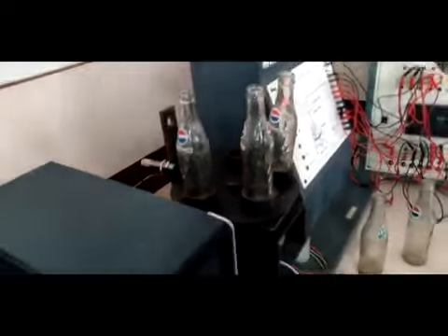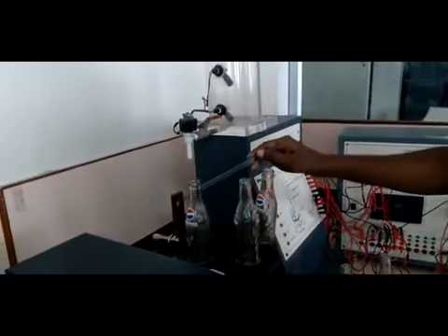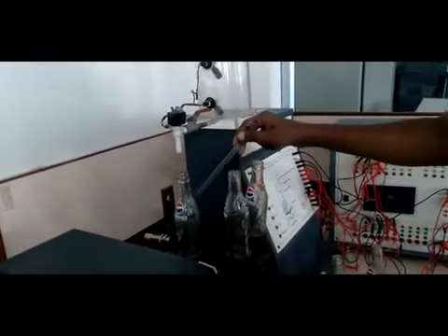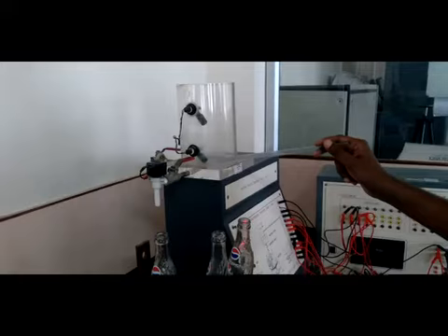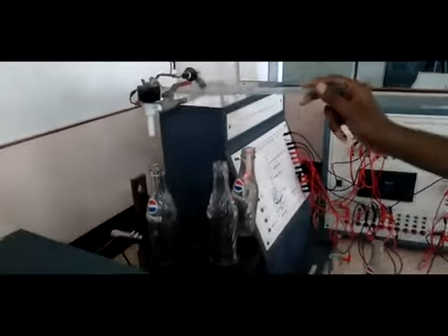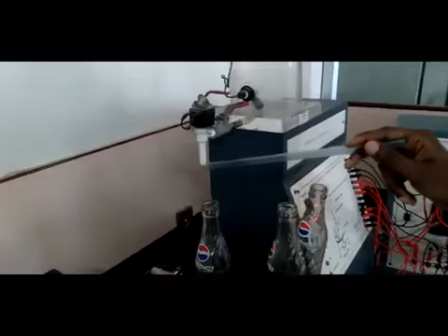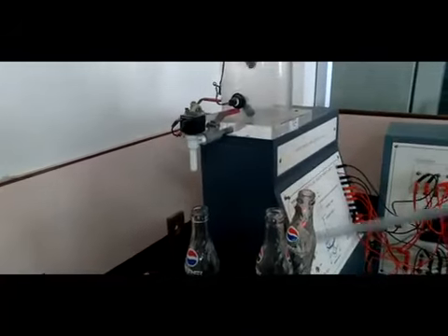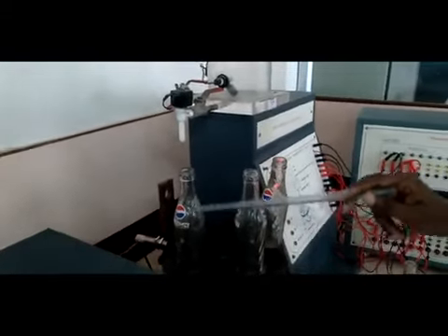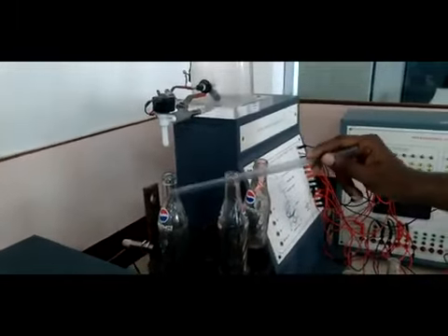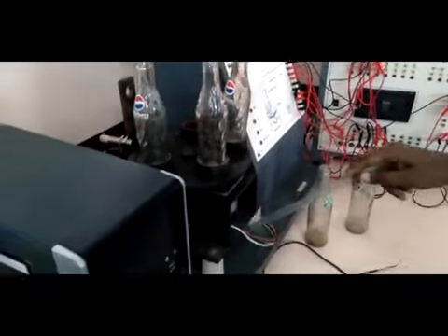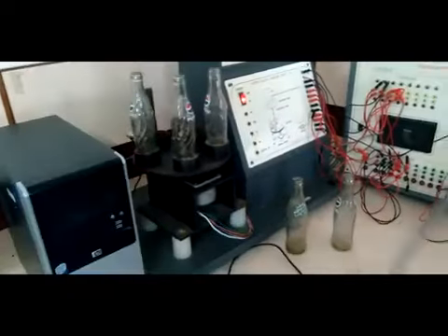So these are the sensors available. We have a bottle sensor, which is an IR sensor, then we have a proximity sensor which senses the position of whether the bottle came or not, then low level and high level sensors for the overhead tank. Then we have the outputs. There are 2 outputs. One is the solenoid valve, which will turn on or off the fluid coming in. Now if you want to fill this tank 100 ml or 200 ml, that will be made through a PLC program. So timing will be made as a logic for filling this particular system. Another output is the stepper motor, where a step angle is given for rotating this system.